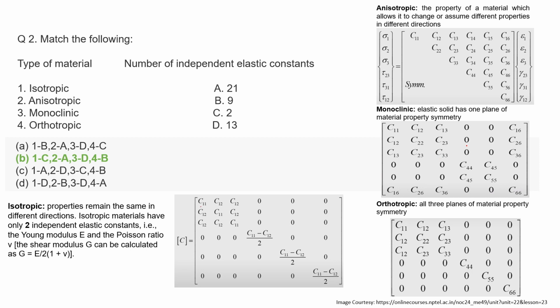After 36, we consider symmetry. As you can see, the stiffness matrix constant C12 will be equal to C21. That is according to the first law of thermodynamics. As we consider the work per unit volume of two types of stresses, we can see that the constants are symmetric.